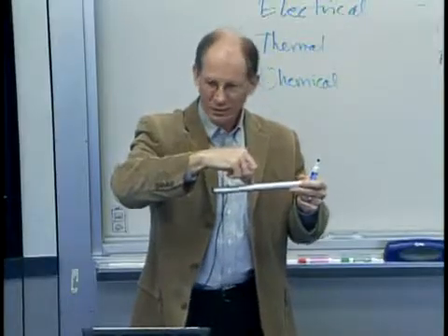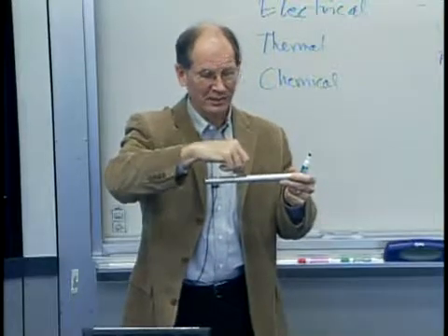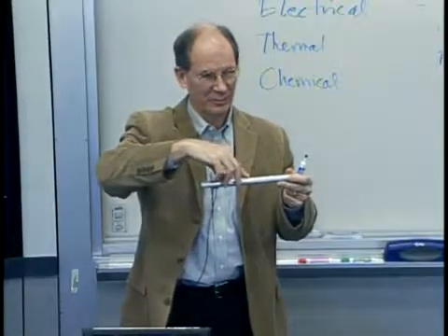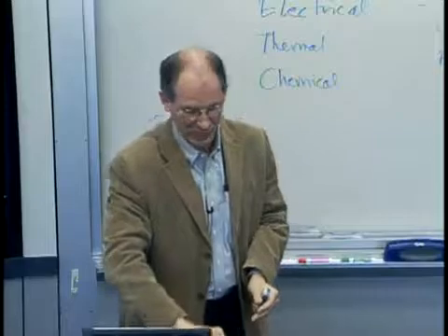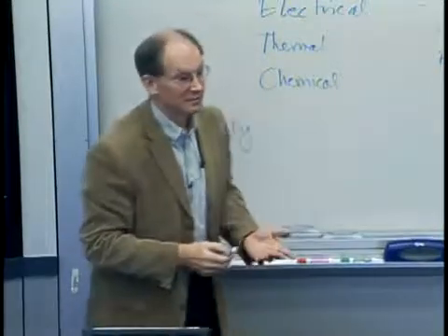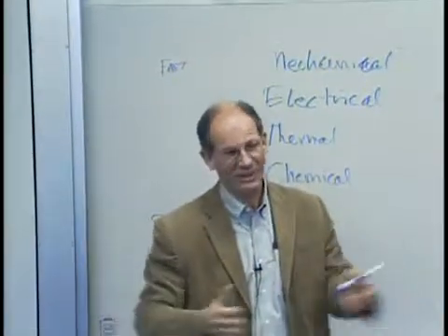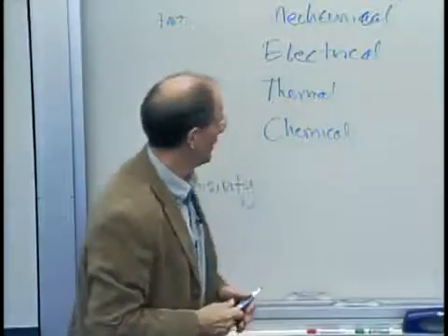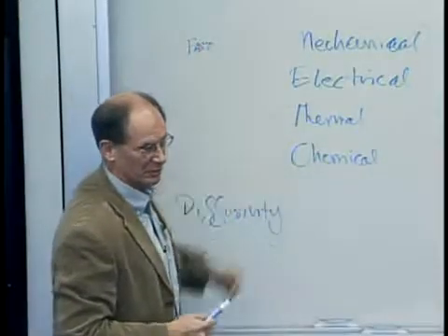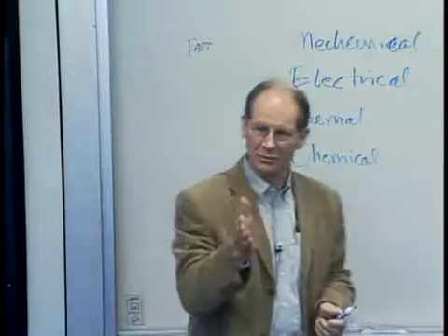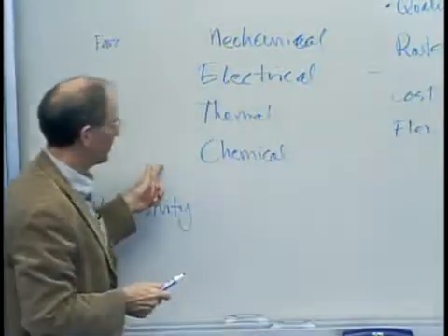How about if I put a thermal source in there? Yeah, and the worst part is not only does it dissipate, it just keeps dissipating. It probably never reaches equilibrium, so it's really going. How about a chemical reaction? One of the problems we have with that, of course, is if you do thick etching, you have undercutting because it doesn't go there, but it's going there. It wants to go everywhere, and other things like that. So again, you have different diffusion characteristics here, depending on what's going on. So your ability to control the shape, to get a minimum feature size, to get a level of precision, will vary depending on what you have here.